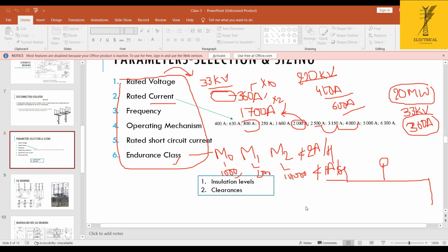So when you are preparing all these things, you submit them to the client and the manufacturers. So you sent to 3 manufacturers, X, Y, Z. Now X, Y, Z revert to you based on your request with some documents. One is the GTP, guaranteed technical particulars, where you can see all the isolator ratings.